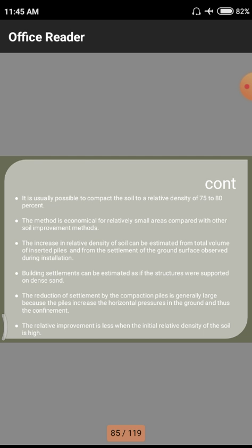Because we are using a huge amount of vibratory methods and static methods, so that some amount of vibration is flowing to the nearby field. If there are any nearby structures located next to the field, we need to have some clarity on the particular building, such as how much depth of foundation there is, and whether there is any effect on the structures.